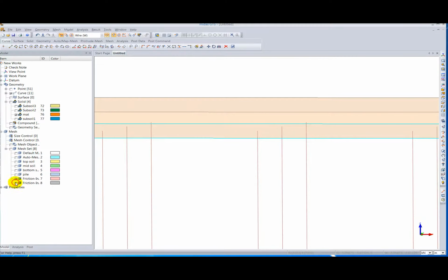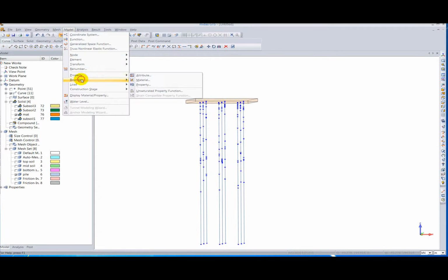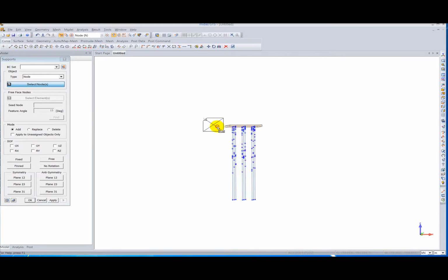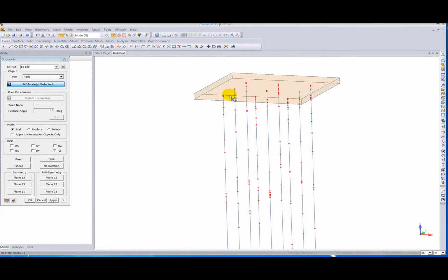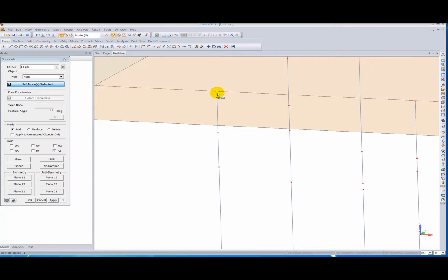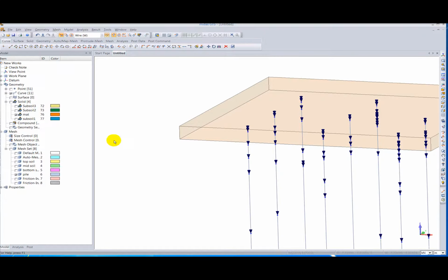The next step is to go ahead and turn on the piles, and then just apply that boundary condition that I mentioned before. We don't necessarily need to apply the whole entire boundary conditions to the whole pile, but let's call this pile boundary condition pile and rotational constraints. These rotational constraints are used just because we introduced these beam elements here and here, but they have no constraints whatsoever. So we'll just apply this condition here and click OK.